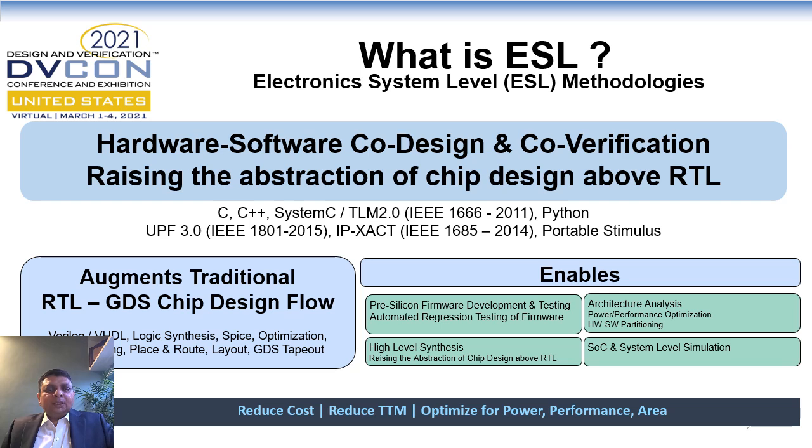ESL methodologies are not supposed to replace the traditional RTL to GDS flow. These have to rather coexist and augment it further. These enable us to perform various operations which are not typically feasible using the traditional methodologies, like pre-silicon firmware development, architecture analysis and optimization quite early in the cycle, high-level synthesis, and SoC and system level simulations.